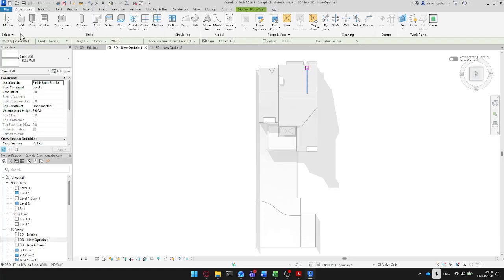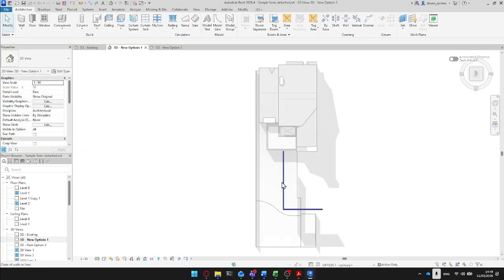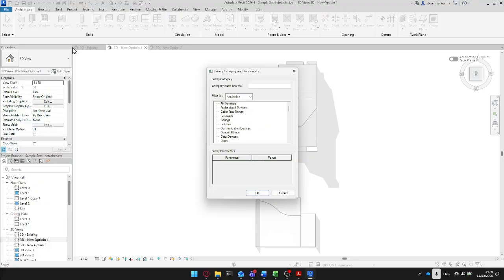So, if you've used Revit before, you probably use this to make walls. That's boring, because we make straight lines and boxes, and people tell you that Revit limits creativity. Instead, what we're going to do, for funky stuff, is architecture, component, model in place. This is where the fun stuff happens. We're going to use wall for this. You can change this later, but it's easier to make sure you have the right one selected to begin with.